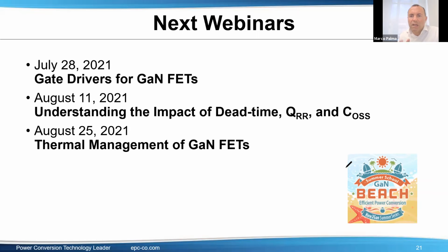scale package. So then I can answer also one question that just came in here, which is about basic silicon. Our technology is a silicon wafer. On top of it, we build the gallium nitride circuit or discrete device, and then we passivate everything. So really the silicon is just a mechanical carrier, and it's also a thermal carrier.